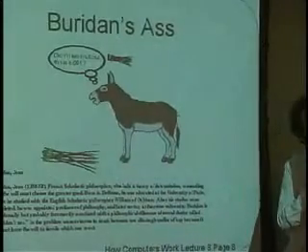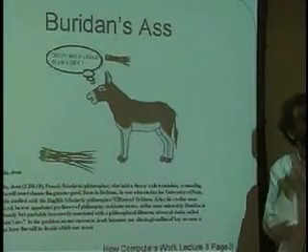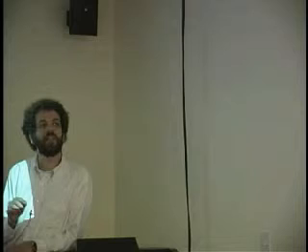Well, somewhere there will be an equilibrium point, again, where the attraction of the two is exactly the same in the little mind of the donkey. And then you say, okay, well, what we're going to do is we're going to wait so many weeks, and if the donkey hasn't made up his mind, we're going to give him a kick to one side or the other, right? But what happens in that case if just before we're about to give him a kick, the donkey says, oh, I've made up my mind? What do we need to do in that case? We need to decide which came first, our little timer that says the donkey's run out of time and it's time to give him a kick, or the donkey making up his mind.